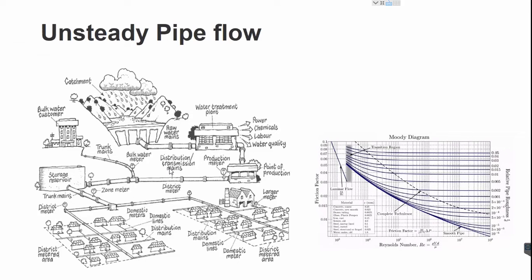And because pipe flows are very important in our societies, during the last century we were able to develop some engineering models which are useful to predict the friction factor in terms of the Reynolds number. So here we can determine the friction factor based on the Reynolds number we have using a diagram like this one, the so-called Moody diagram, which is based on an equation called the Colebrook equation.